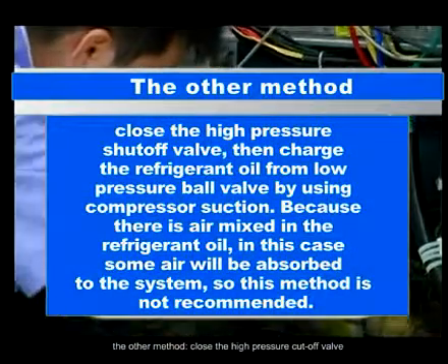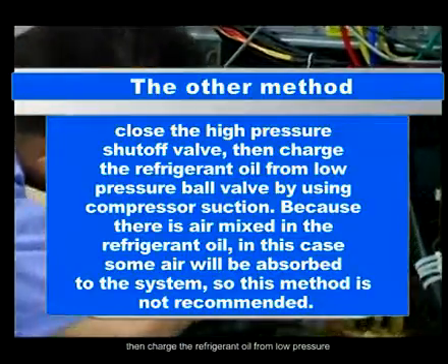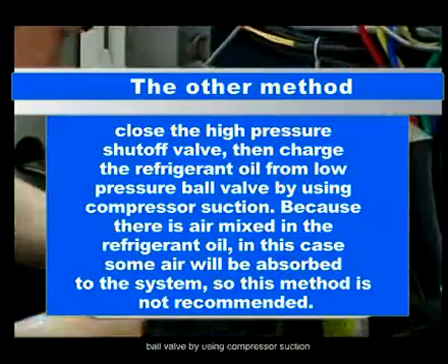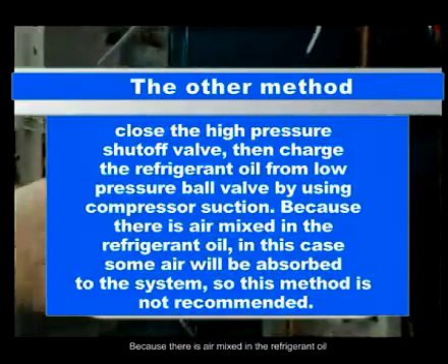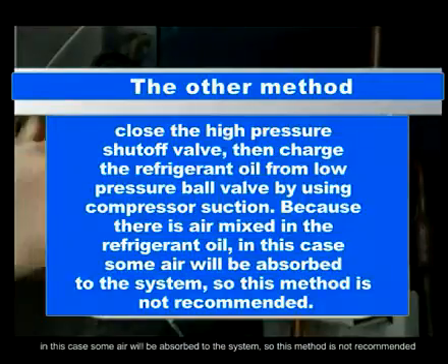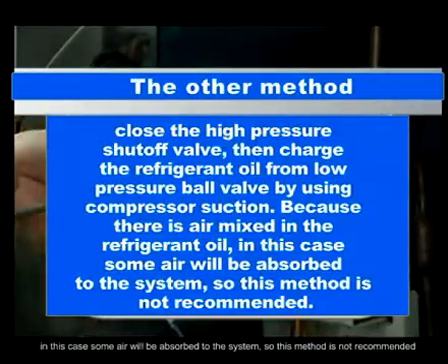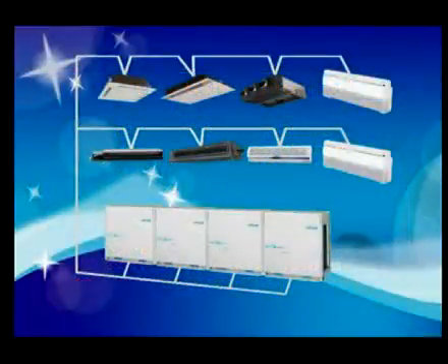The other method: close the high-pressure cutoff valve. Then charge the refrigerant oil from the low-pressure ball valve by using compressor suction. Because there is air mixed in the refrigerant oil, some air will be absorbed into the system in this case, so this method is not recommended.